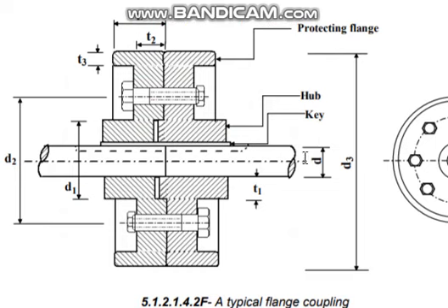This flanged coupling, when we are drawing in the drawing sheet, you draw like this. Normally these flanges are made of cast iron. Okay, you see these two flanges are not identical. One has a kind of recess here. That recess will be circular. In this drawing it is looking like this, and in the other there will be a projection, one recess, another projection, so that they will exactly mate together.